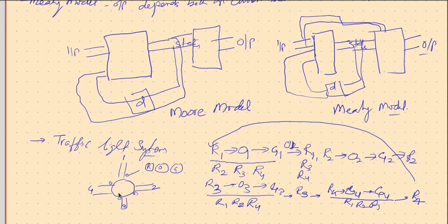And if we can control the output through the traffic, then the system looks into the input, and the appropriate output will be turned on or off depending on whether traffic is there or not. And the duration of on depends on how much traffic there is, and so on. So such a model will be a Mealy model. Many more examples to follow.